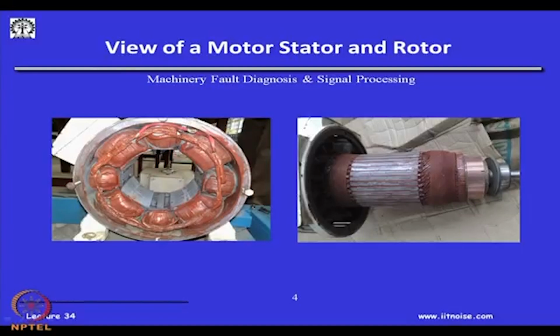and if the heat is not dissipated, the temperature is going to rise. Once the temperature rises, it may have many effects. It may heat up the coils, it may degrade the insulation, it may damage the bearings, because the lubrication in the bearings will get baked. Once this lubrication gets baked, there will be hard particles, and hard particles are going to scrape the inner surface and the bearings will become rough. So, one leads to another when you have a fault developing in an electrical motor.